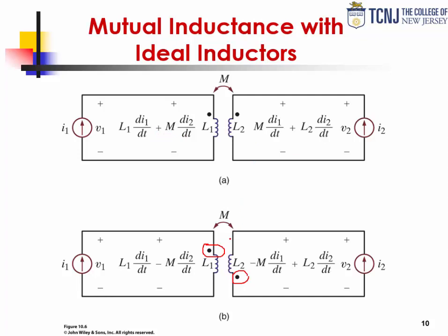And when we have a situation where the windings in the primary and the secondary are such that the polarity of the voltage in the secondary is the reverse of the polarity of the voltage in the primary, we put a dot on the opposite side of the secondary winding, and that corresponds to the equations where we have minus signs in front of the mutual inductance terms.